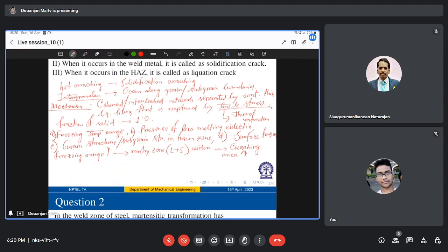Okay. Now, in terms of the effect of impurities such as sulfur or phosphorus in steel, it also widens the freezing range considerably, but without producing a large volume of liquid to permit that backfilling. Such residuals tend to segregate at grain boundaries, where diffusion rates are almost always higher due to the more open nature of the lattice structure. I'm not going into detail of those things, but yeah.